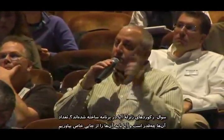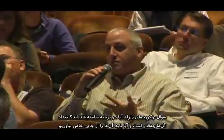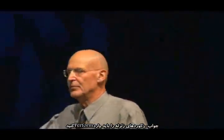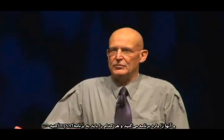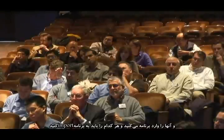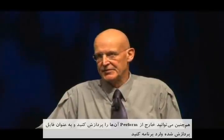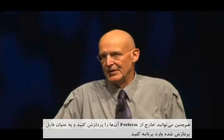The earthquake records, are they built in, or do you have to get them from some source? Where do you get them from? About the earthquake records, you have to input them into Perform. Typically you'll have the earthquake record available as a text file, and then you import it, and you have to import each one. But you can set up a library of earthquake records, and you can use them across different structures. It is also possible to process them outside Perform and then just bring the processed files in. It's not a major issue unless you've got hundreds of earthquakes.